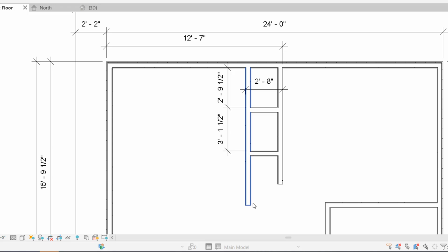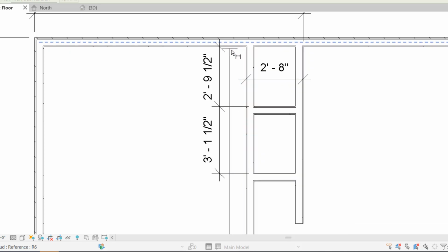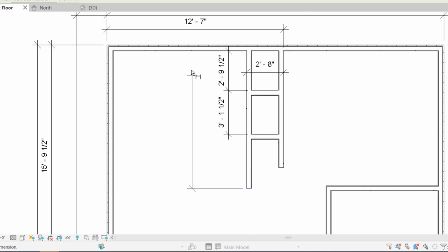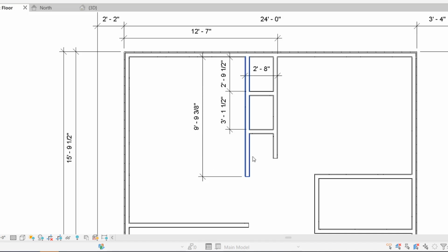So now that I have that, that covers all my walls. Let's get the full length of the wall. I'm going to again cycle to the interior face. I was easily able to select here because there was only one option. I don't want to go to the center of the wall. Tab, and I go to the interior. So that wall length should be 8'7".